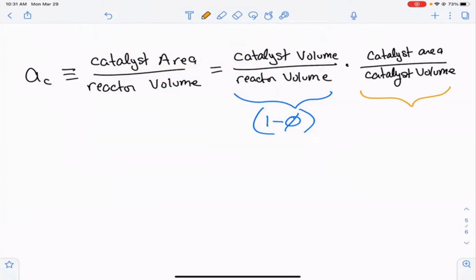Now for spheres, right, which is the thing that we've been thinking here, well, this term for a sphere is just the area of the sphere over the volume. So that's just pi times the diameter over 2 squared, or we've actually called this d sub p, divided by the volume, which is of course just 4/3 times pi times the diameter over 2 cubed.